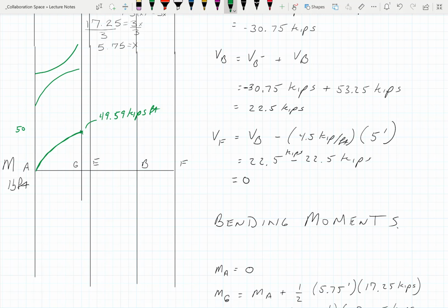Now, what about that shear diagram? When I told you that most maximum moments, or moments likely to be the max, occur at a shear of 0, shear and the slope are the same thing. Just to show that there is some relevance to stuff you learn over in the math department. But either way, we're good there.